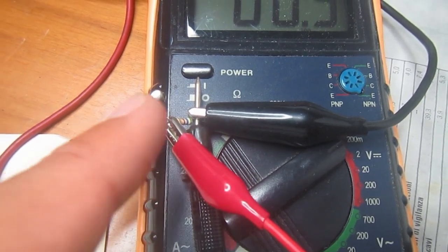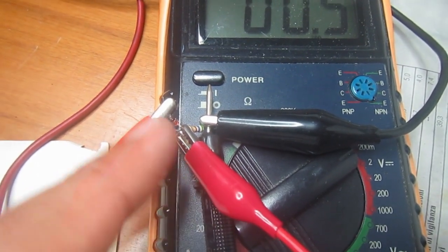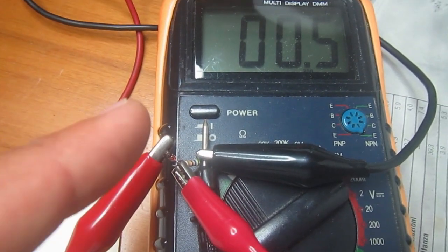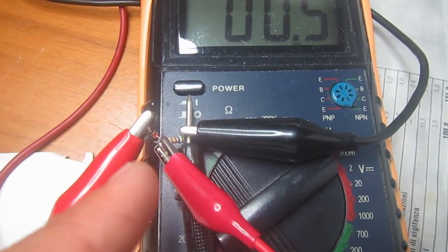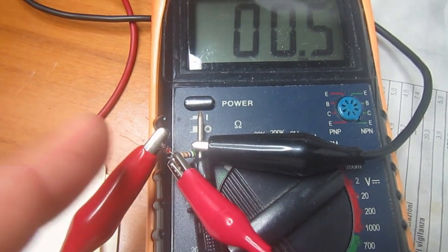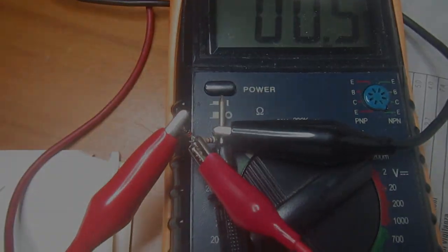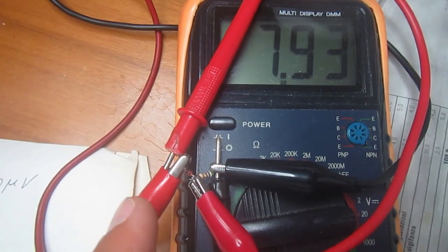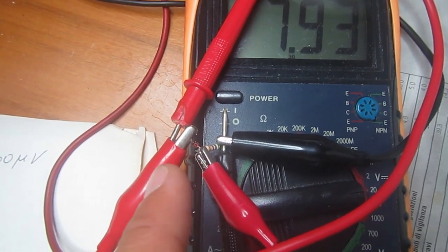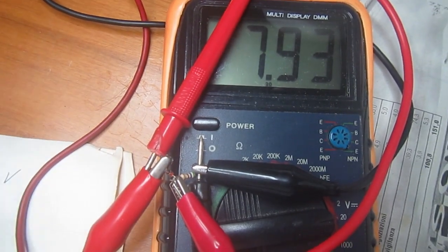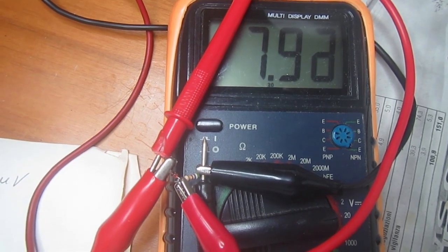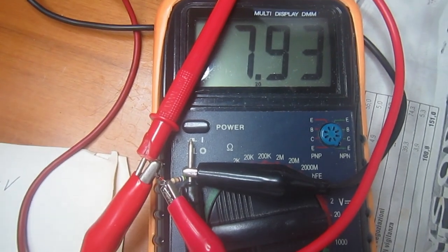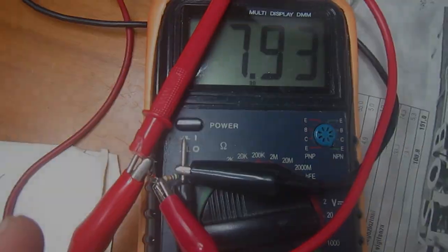Now, last step is measuring the voltage out from the power supply and see if this zener diode is supposed to be conducting based on its turn-on voltage or not. Well, it's 7.9 volts. Now measuring the output of the power supply, which is, well, I don't know. I think it's surely okay for an 8.2 volt zener.